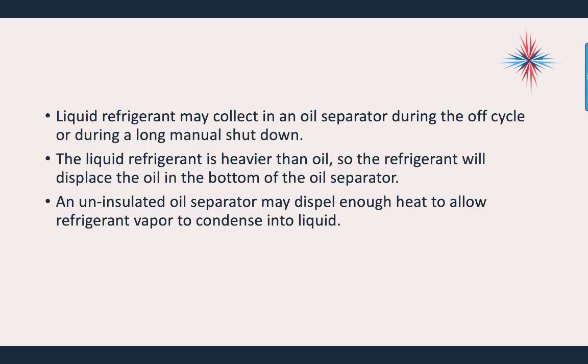Liquid refrigerant can sometimes collect in an oil separator during the off cycle or during long manual shutdown periods. The liquid refrigerant is heavier than oil, so the refrigerant will displace the oil in the bottom of the oil separator. An uninsulated oil separator may dissipate enough heat to allow refrigerant vapor to condense into liquid. This is especially important in cold climates.